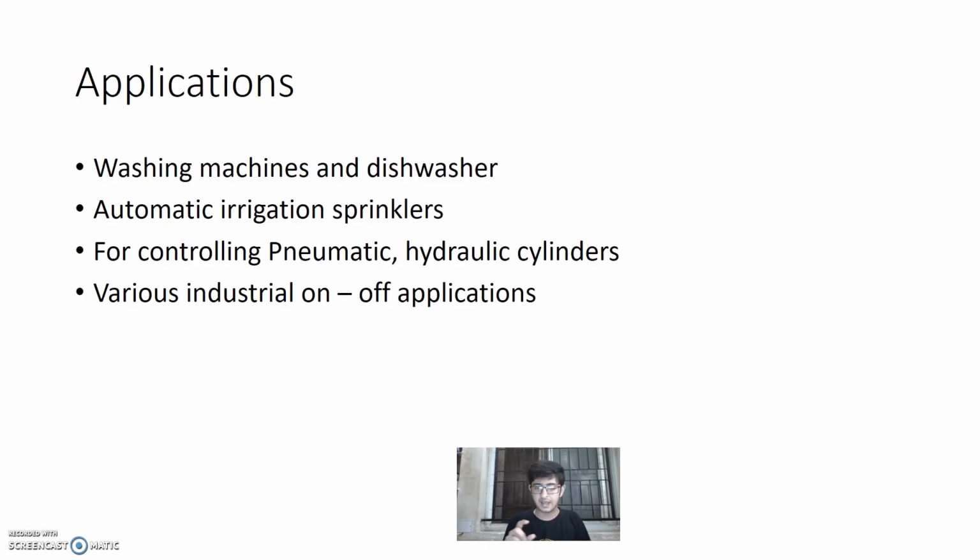People have also discovered many accessories for solenoid valve. If you are using air as your fluid, it will create a lot of noise, because if you are pumping air at 2 bars or 5 bars pressure, obviously there will be a lot of air noise created. So in a three-way solenoid valve, we have a muffler at the back. You can attach that muffler to minimize the noise created by the solenoid valve.